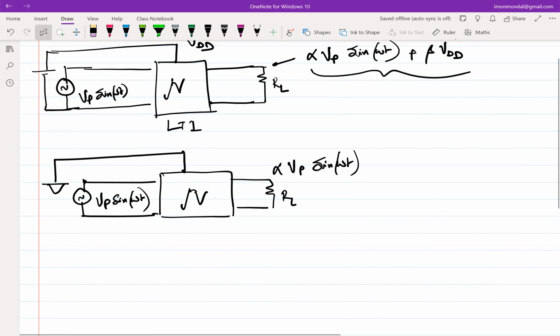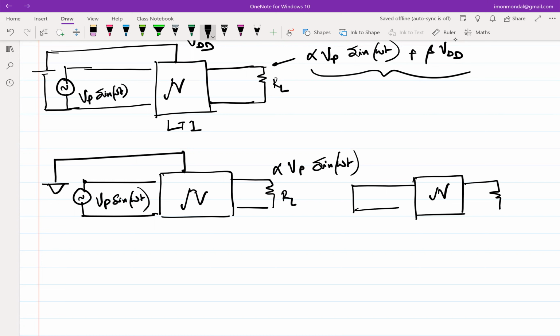And in experiment 2, you will short the input and apply VDD. And what should you get at the output? Beta times VDD. Great. So superposition essentially means that whatever I get after each of these two individual, unrelated experiments, I can add up the outputs, and the final output will be as if both the input sources were there in the first place.